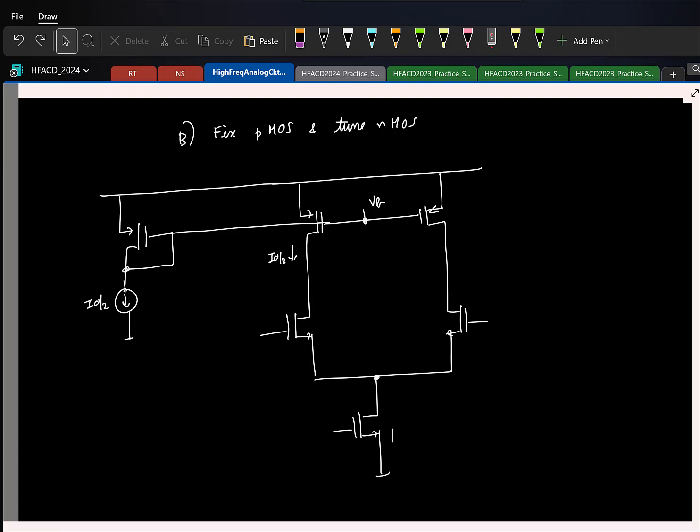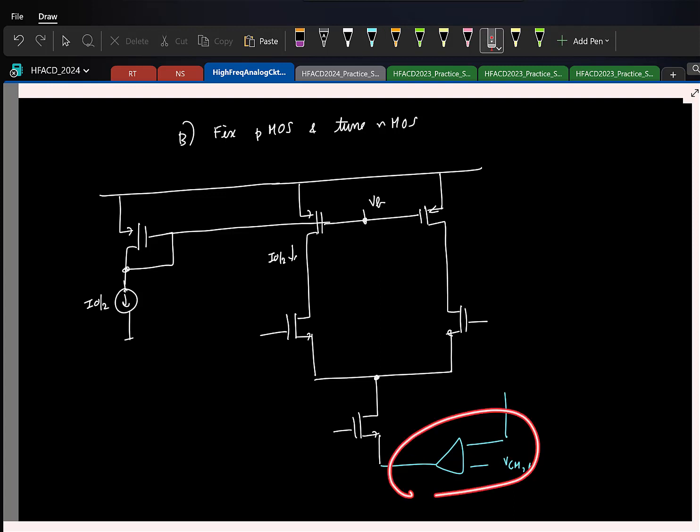See, here the goal is to basically control the current in the nMOS transistor. Now tell me, the current in this transistor depends on what voltage? Strictly speaking, gate to source. Here the source is grounded, right? But that's what we can control, the gate. That's what we typically do. But you can also actually control the source voltage, right? And of course, one thing is you can do the same thing. Again, have an op amp, and so on. But now the source voltage here, do you think it will be typically a small voltage or a very large voltage? You want it to be very small, so this might not be a great idea to do.